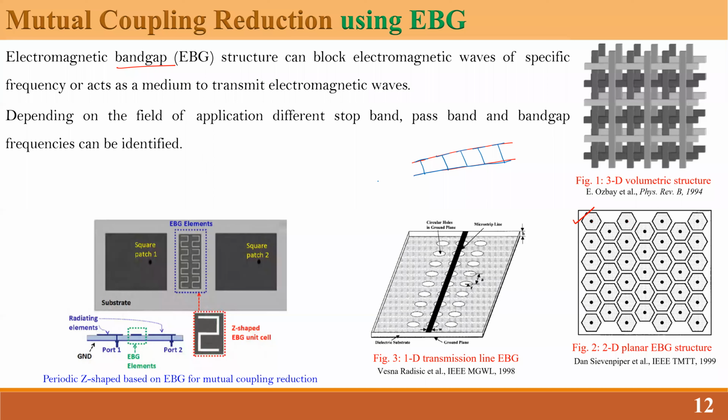Now, if I quickly write the impedance of this particular structure, the simplest way I can write it is Z, obviously a function of omega. This is nothing but j omega L divided by 1 minus omega square LC, right? And obviously the resonance frequency f0 would be 1 by 2 pi times the root of LC, right? Now you understand that. So obviously this is giving us some kind of a resonance frequency, some f0.